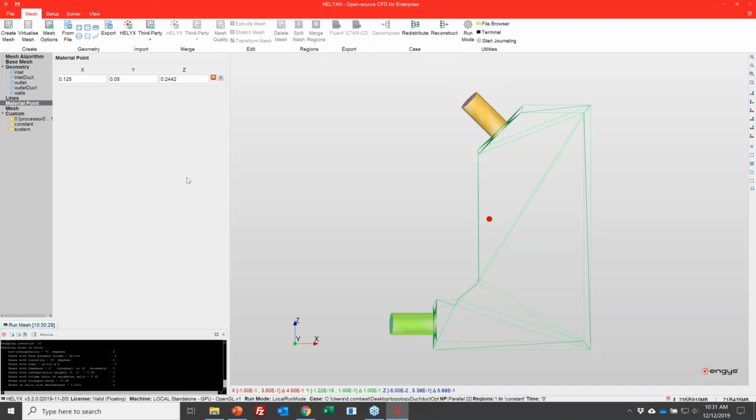We provide the mesher with this information because it's an iterative mesher. It will create layers, create refinements, and as it's progressing, if it creates something that would produce a lower quality cell, then it can revert itself and take another path.